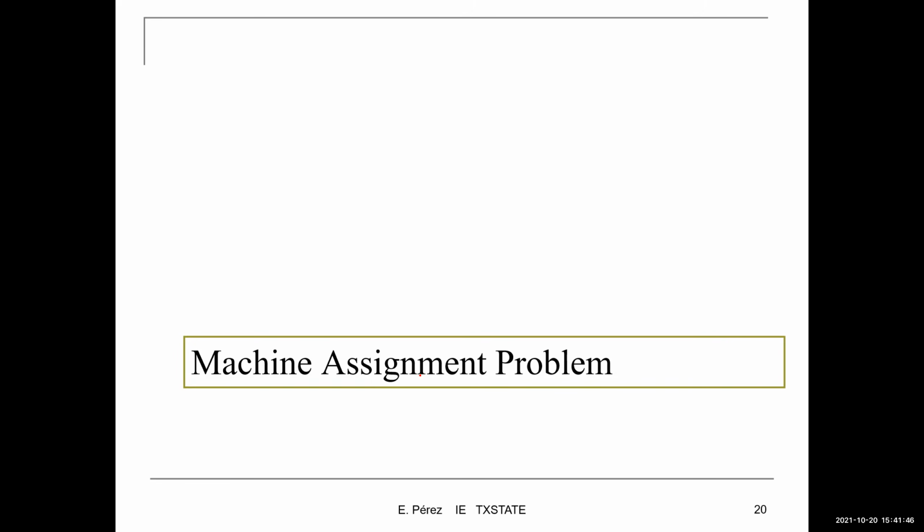If you have multiple machines, you see that there will be some instances in which this person is not going to be able to take care of both machines or both lines at the same time. So there will be time periods in which the machine will be busy and will be idle, waiting for this person to come up and set up the next batch and so on. So we need to have an understanding of, if we have this many machines, how many people at least we need to manage the operation of these machines.